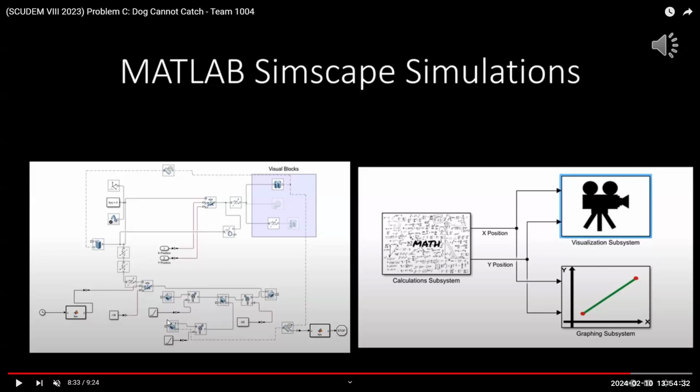Other than that, everything else, we've got this down here, which is our brick solid for the ground. And then this system over here is our system for Fritz, which is a bunch of different body pieces connected by revolute joints to give them motion. All of the splitting up of the solid we did in SolidWorks. So we had a SolidWorks 3D CAD file of a golden retriever. We then took that and used the split command in SolidWorks to split it up into different body parts and save those as different files. We then bring those different files into MATLAB and just stick joints on them to make them function.